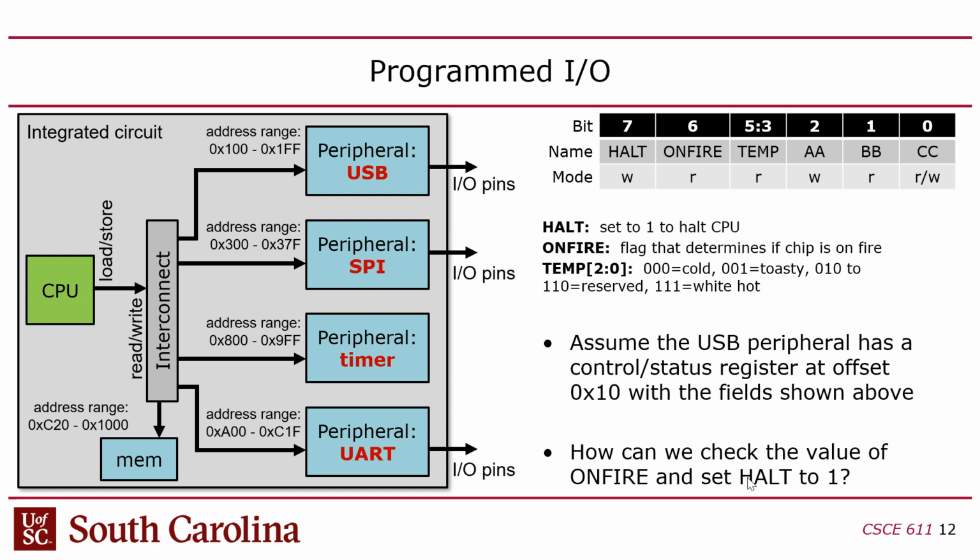Now you might say, whoa, hold on, are we writing this in assembly language or what's up? No, you would load that into a C variable, which ultimately would be in a register, but you don't necessarily write it that way because you generally write in C with embedded systems. You load that into an 8-bit C variable, and then your goal is to take those 3 bits out and interpret that as the temperature.